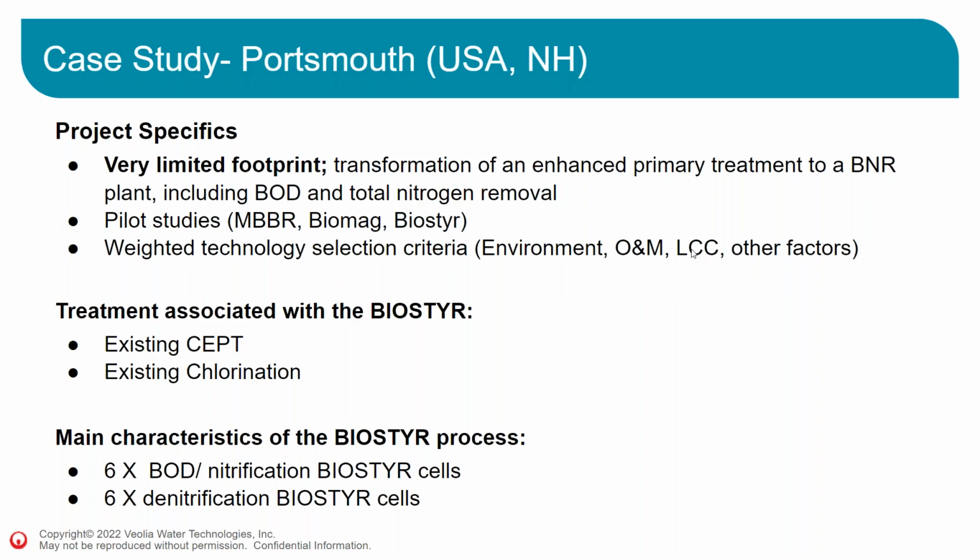treatment that was working well for what it was doing, but at some point they needed to do complete nitrogen removal. So they needed to increase the capacity. Well, they needed to change the process to allow nitrogen removal. But they were very, very limited in the footprint. It's on an island. There's a lot of parks, historical districts, and everything around. So they were very, very tight to do some biological treatments, secondary biological treatments. They did several pilot studies. They tested MBBR, BioMag, and Biostyr, and doing an analysis of the three technologies, they decided to go with the Biostyr.